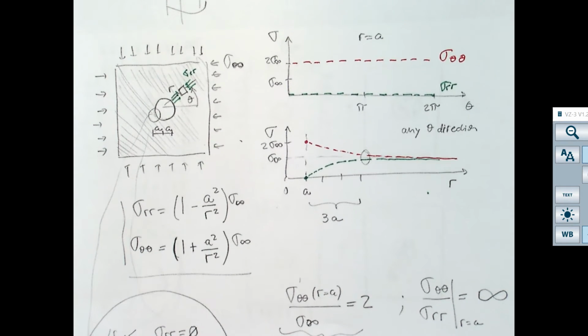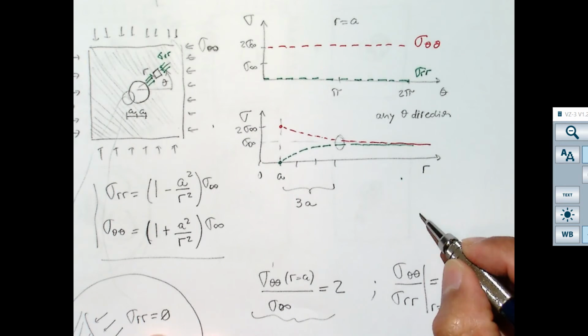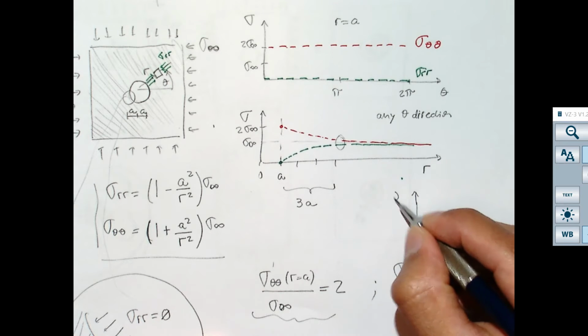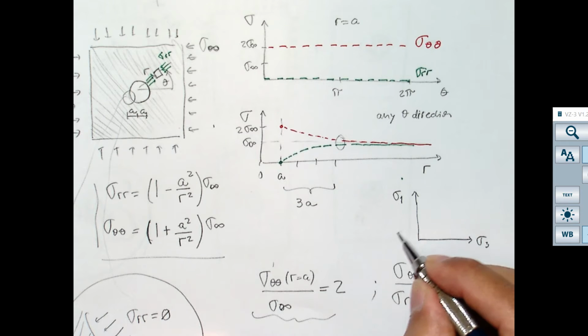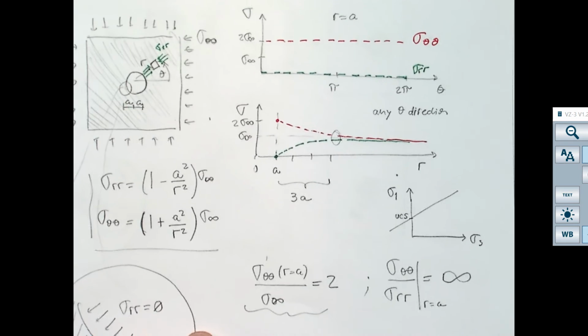And the last thing that we said, because of that, having a radial stress equal to 0 at the wall of the wellbore and a hoop stress which is not 0, the only way to have such thing stable would be that your rock has some finite unconfined compression strength.